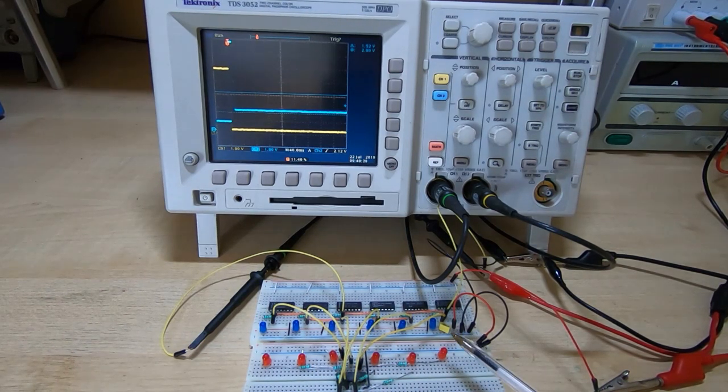And what I want to show here, very briefly, is the issues caused when different families of TTL chips are mixed within the same machine. Now sometimes mixing different families can be a very good thing if you have a specific need to do it, but 99% of the time it's a very bad thing. And that's what I want to show in this video: what I've been investigating so far and trying to eliminate are problems caused simply by inappropriate mismatching of different IC family types.